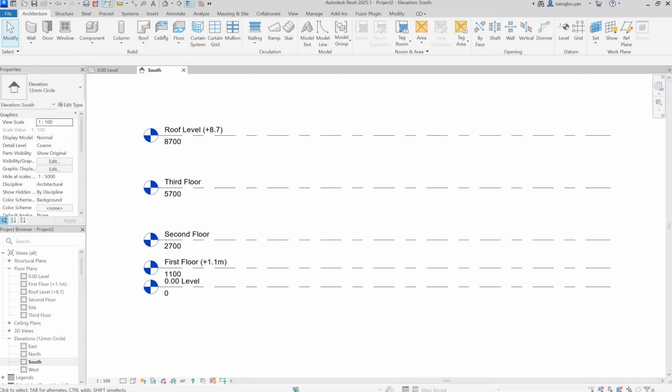Here I just share some differences. What you need to notice is that you just follow this grid line distance and this grid line distance. This 2.43 is based on this location, and here it is not 2.4 but 2.1, because it doesn't require a grid line, it's just for the internal wall between 2 grid lines.